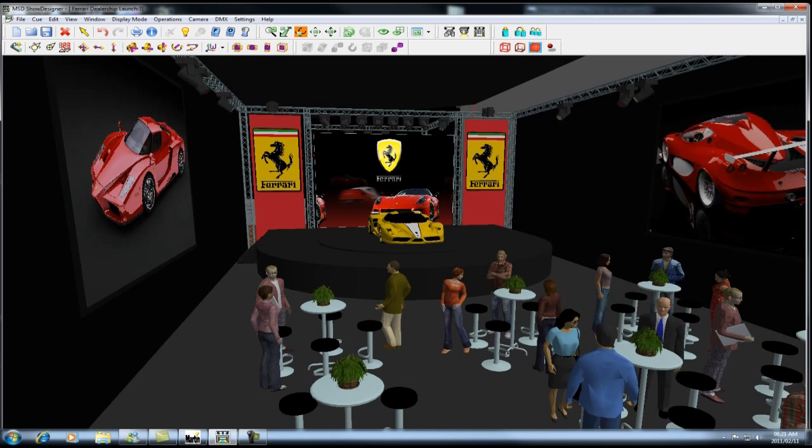You can also double check to make sure that the lights are receiving DMX by clicking on their fixture, going to Spot Beams, and clicking on Always. If you click on Always, you will see the light source there. If there wasn't any DMX, those beams would be black, which means there is something wrong and you have to double check it. Let's put them off for now.